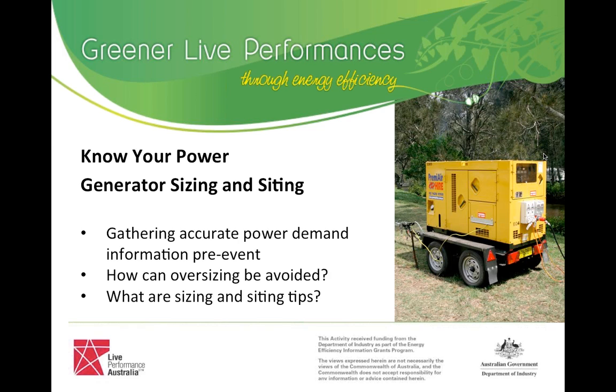So at the outset, you're going to have a higher fuel consumption for a larger generator. So the risk is if you're not using the capacity, that's when you're becoming inefficient. Correct. So I guess that overall for an efficient event, you want to have smaller power demand. But if you have certain production values and you've got things that need to be powered, you've got 100 food stores and they all need to have Bain-maries or whatever. Yes.